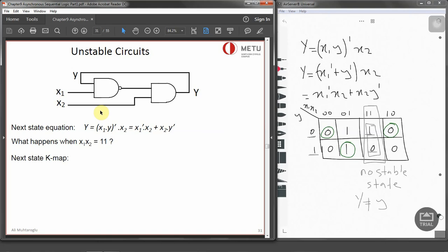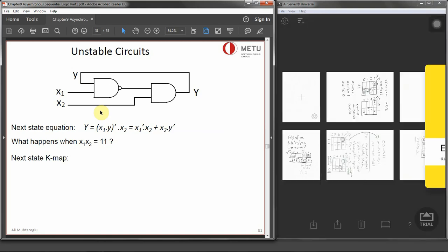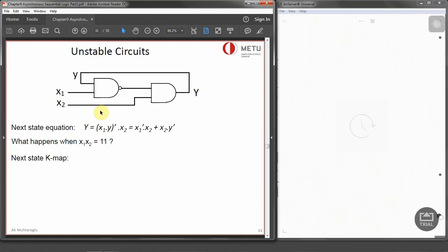I don't know if you do remember the SR latch from chapter 5, sequential circuits, but I'm going to make a quick revision on that. Now, SR latches, we have got NOR gates and we have got a reset input, a set input, and the output Q and output Q bar. So the output on one side will go in as an input to the other one, and the output of the other side will go in as an input to the first. This is actually an asynchronous circuit. As we already said, we just need to have a feedback and the present and next state. So Q can be Y, and the feedback coming in is small y.